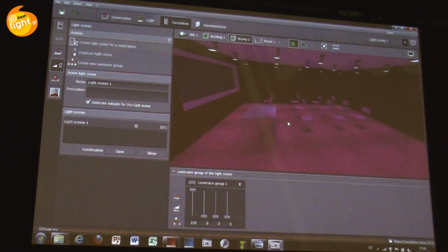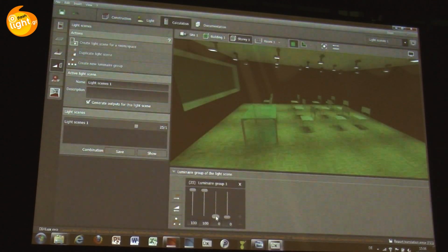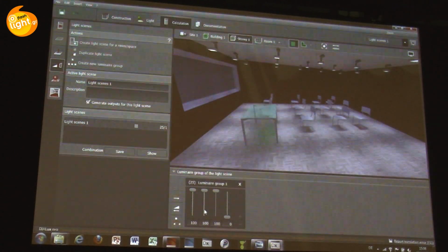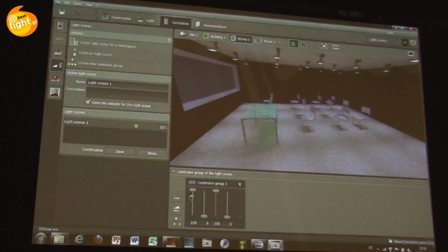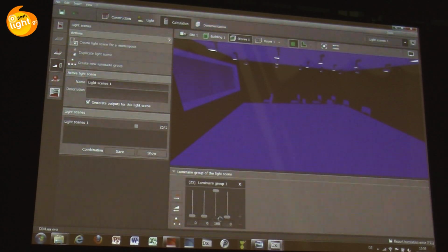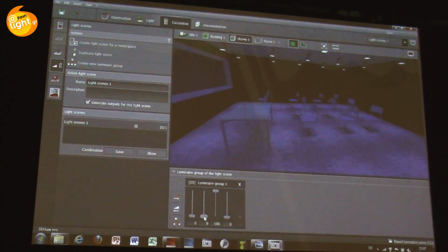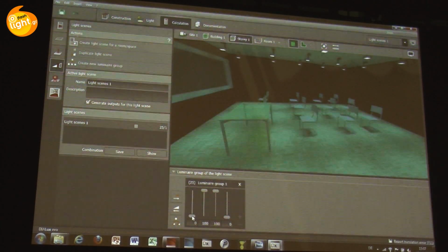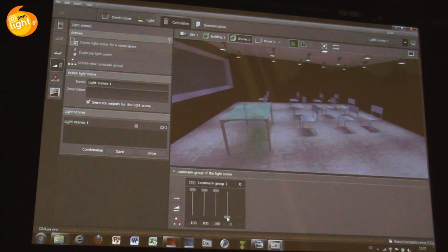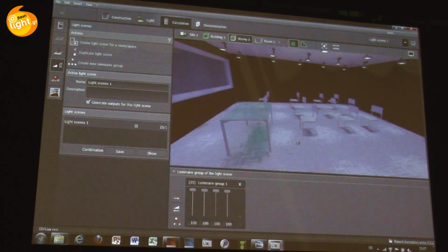It's an online dimming. I don't have to do the calculation once again. It's just once calculation, and then you can dim them individually from each other. Besides the color change, you also have a change in the calculated values, of course. That's clear so far because you have less power when you just use one LED type there. So that's the way Dialux Evo works.